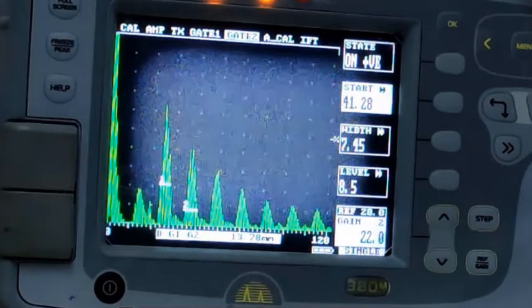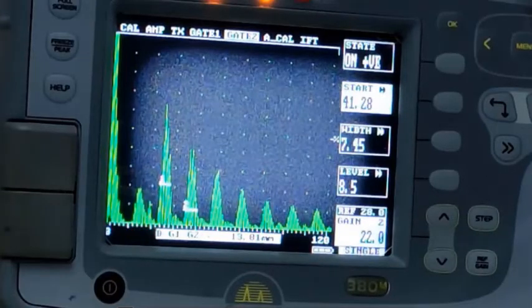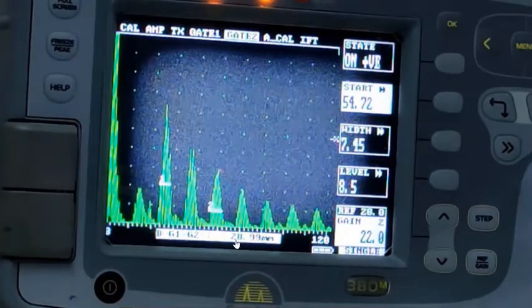Right now it is on the next back wall. The distance between these two consecutive back walls should be close to 14 mm. So this is very close to 14 mm, around 13.8 or so. Let us move it to the next. It should be 28 mm for the next one. Yeah, so that is what you see. This is close to 28 over here, right? This is around 28.9 mm, which is quite good. Move it to the next.